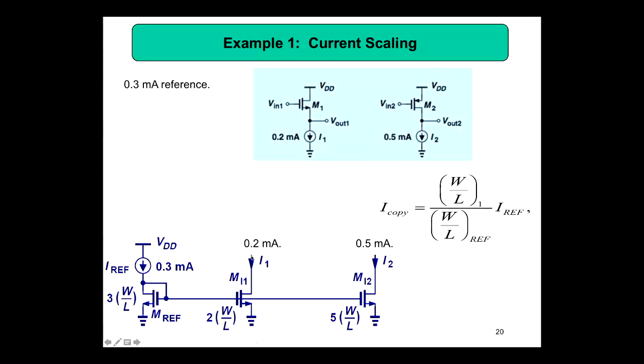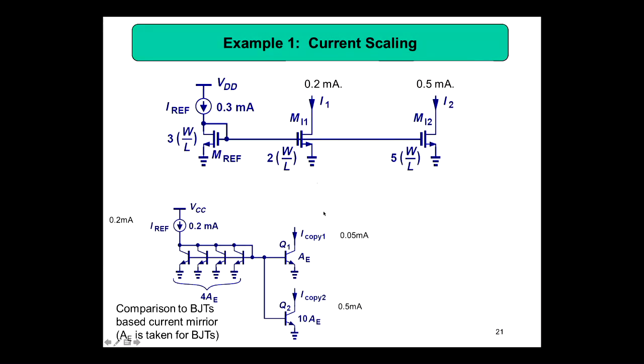So that's the reason. This part you can connect to here, and this part you can connect to here in the chip. That's how we will be biasing current sources. And here we know that when we connect in parallel, for BJT we will be discussing area, but for MOS we will be discussing in terms of W by L.